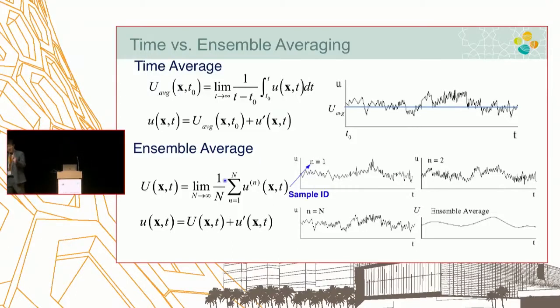A very good everyday example is IC engines. Imagine you're doing time averaging of IC engine information. It'll be flat, right? Doesn't make sense. But if you have phase-locked information at, say, every 10 degrees from top dead center, it'll be fluctuating, but you can get the average quantity. That's Reynolds averaging. That's what we call ensemble average. We run many different realizations and average over them.